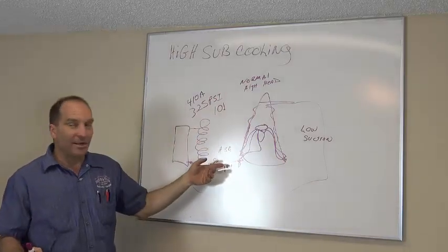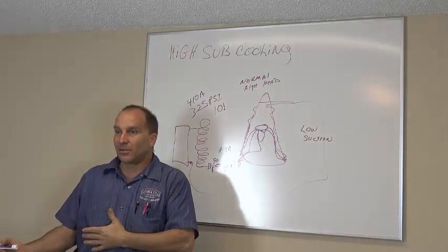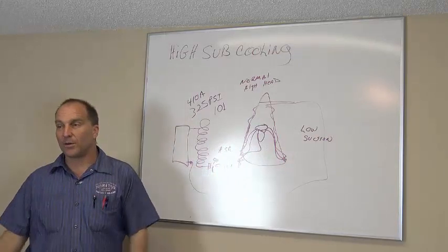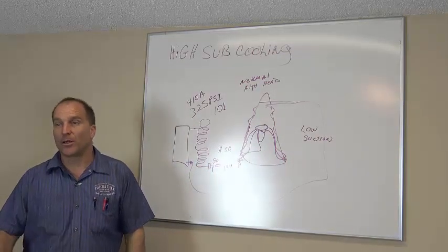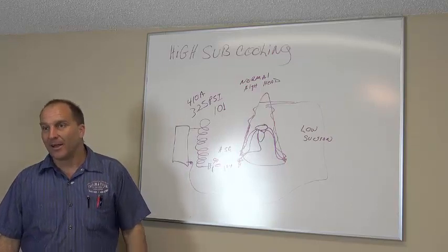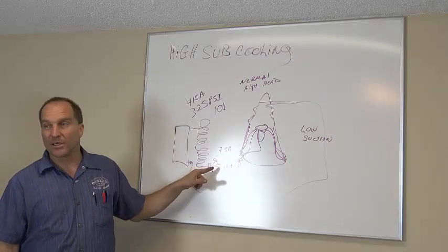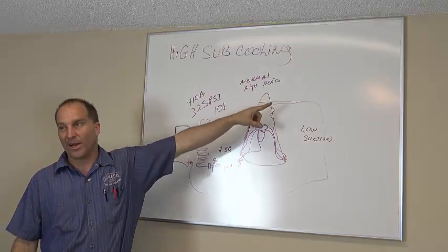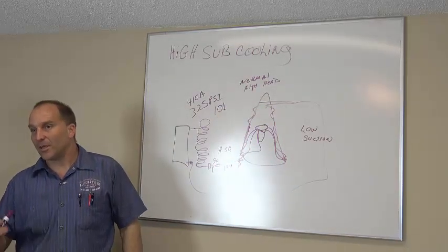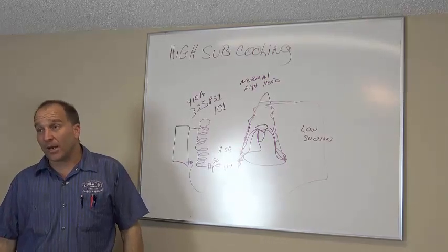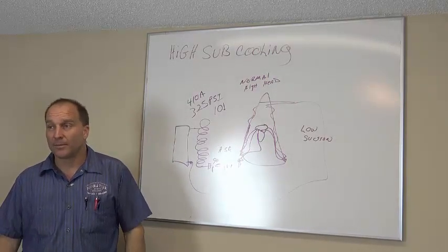If your line is 90 degrees and it's 85 outside, you're actually getting rid of more heat, right? If it's hotter outside, or if it's going through a 130 degree attic, and it's 95 here or 90 degrees here, it'll pick up heat, won't it? Okay? So there is going to be a variation. You just have to understand what temperatures you're in.